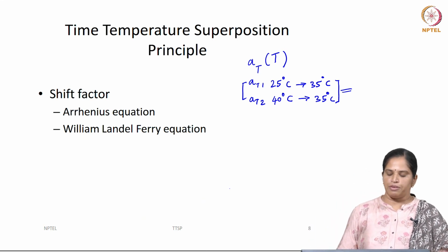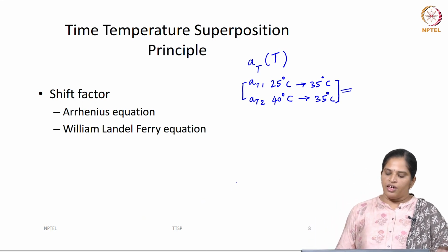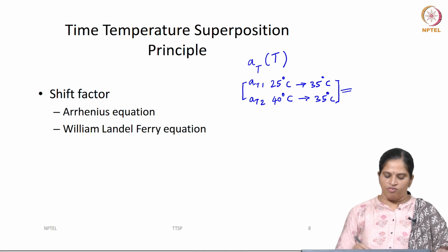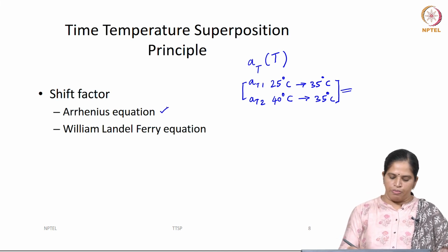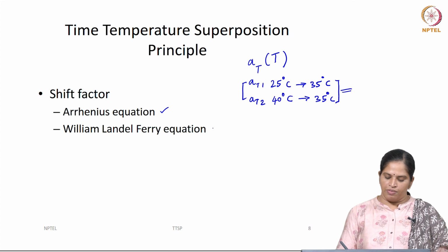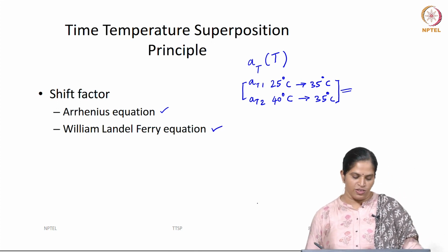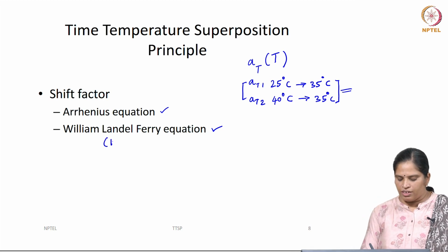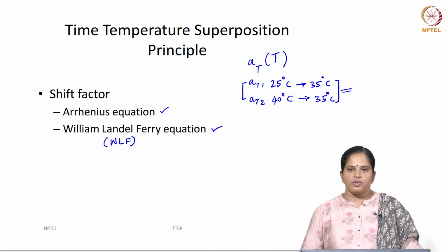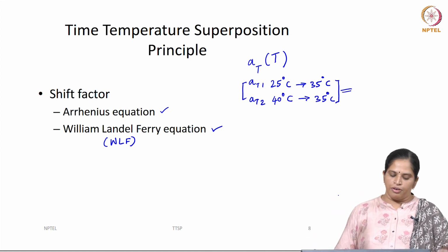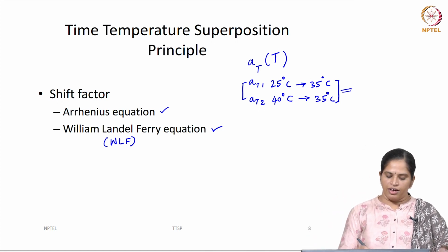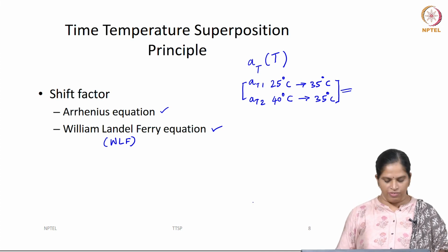Using the time temperature superposition principle, we can calculate the shift factor using two approaches. One is the Arrhenius equation and the other is the William Landel Ferry equation, which in short we call the WLF equation. Now let us see in detail how to calculate the shift factor using the Arrhenius equation and the WLF equation.